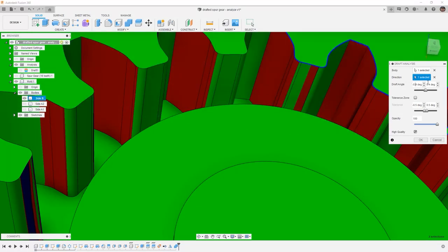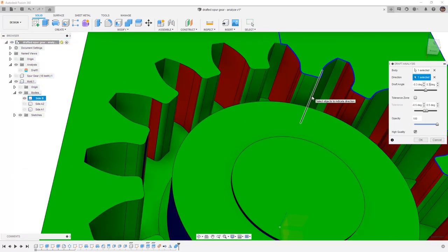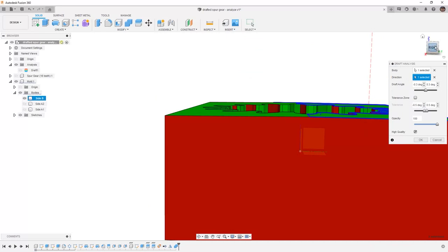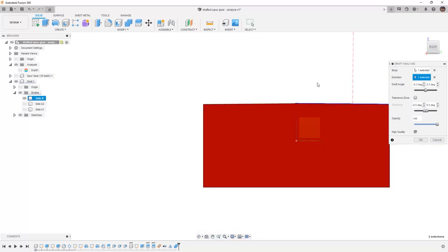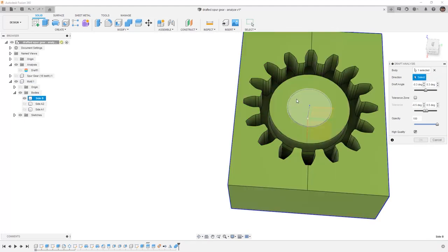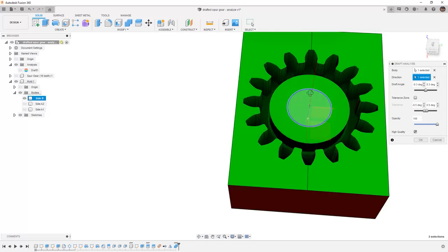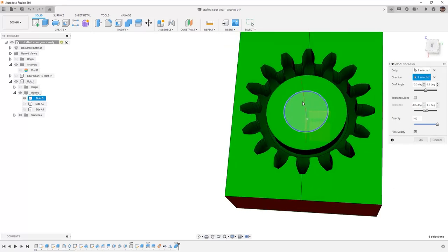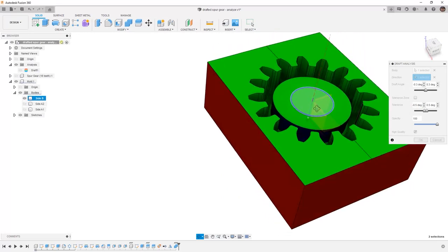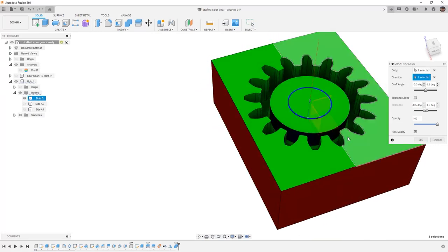If we want to, we can reduce these values even further to get a better idea as to the range that we're going between. We also might need to change things like the direction that we're pulling, noting that what we're doing here is we've selected this face, and if you remember how we produced this originally, that face is already tapered. So this is actually producing a bad result simply based on our selection. So we're going to change the direction selection and make sure that we use this top center face. We know that we didn't draft that to either side in the Y direction, and now everything looks to be green or blue. So this tells me that this is a much better situation.